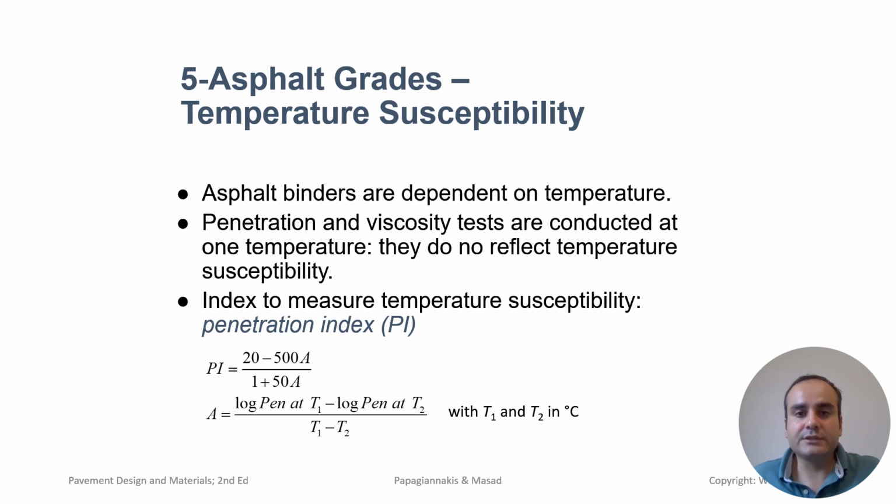At low temperatures, asphalt binders become more brittle and behave like elastic solids, which can lead to issues such as thermal cracking as the pavement contracts. Temperature susceptibility measures the sensitivity of the binder to these temperature changes and helps in understanding how well the binder will perform in different environmental conditions.